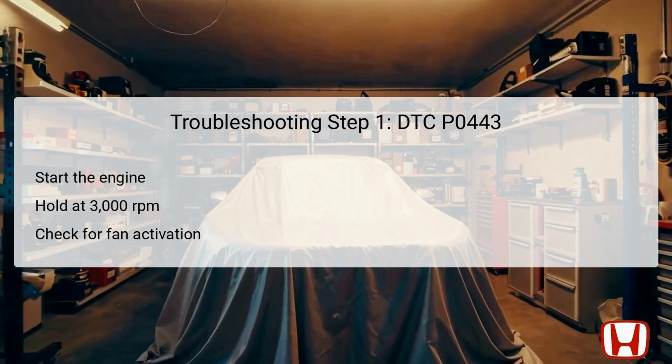It's essential to hold the engine at this speed until the radiator fan activates, which typically indicates the engine is operating at a stable temperature. After the fan comes on, allow the engine to idle for an additional 2 minutes. This step helps to ensure normal operating conditions before proceeding with further inspections, especially as it may prepare the emission system for subsequent tests.